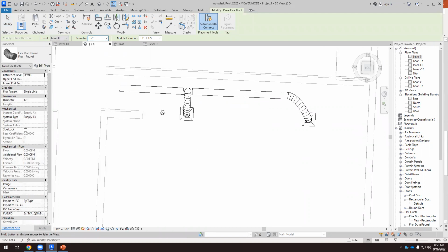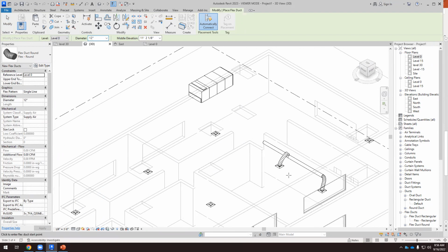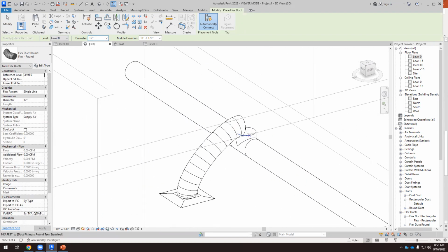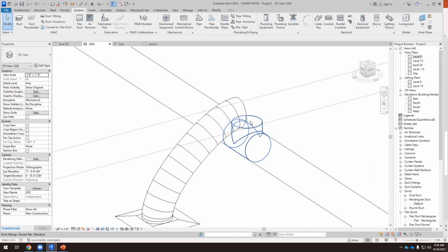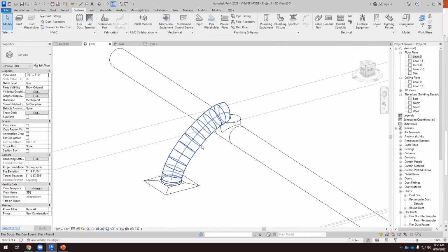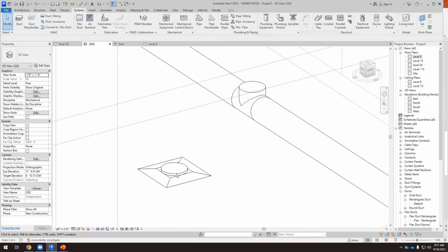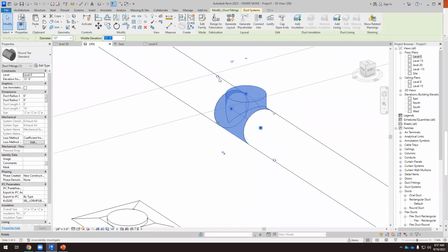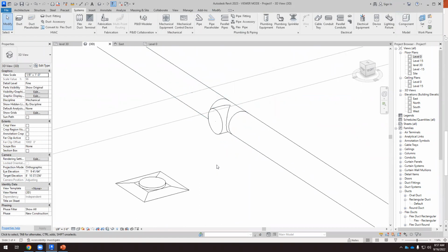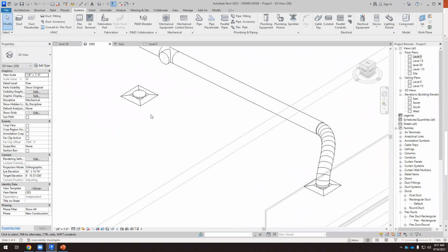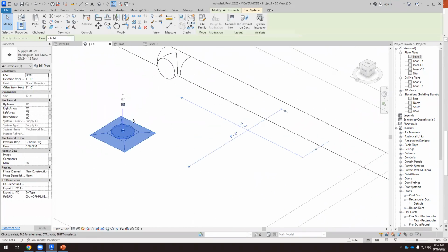And by default, I don't know why, but in Revit, by default, we always have this. And this is not good. You see that it's not good because the angle is too steep. So if that happens, we have to delete the duct and rotate this T. You see that we have rotation here. We rotate the T in the right direction. There you go. Okay, so if we have a T facing the diffuser, now we right click, flex duct,